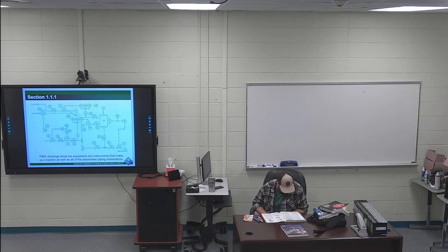The first two sentences are highlighted. When laying out piping, fitters must avoid interfering with other structures and utilities in the plant, such as other piping systems, structural members, HVAC ductwork, and electrical conduit. Avoiding obstructions can be especially challenging because fitters must meticulously inspect existing obstructions and anticipate other obstructions that could occur in the future. Down below, 121, right above where you see page 4, I wrote in there, plan to avoid current and future obstructions.